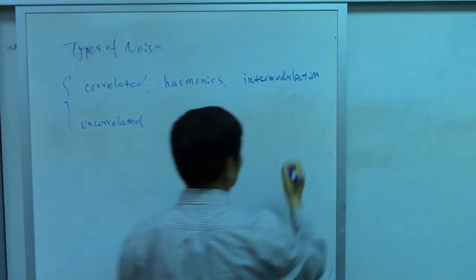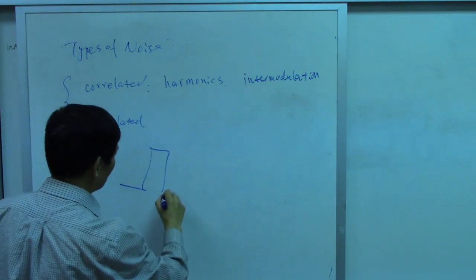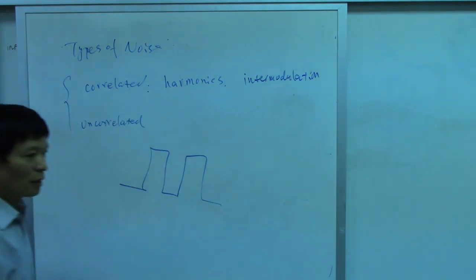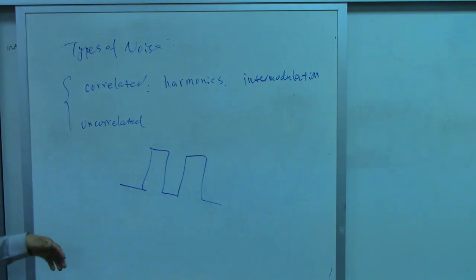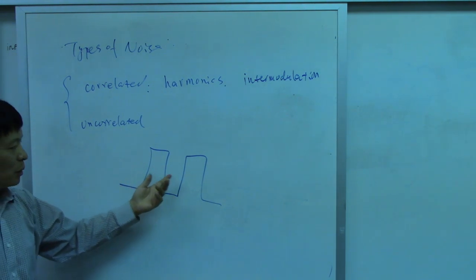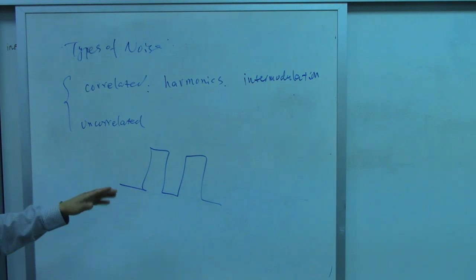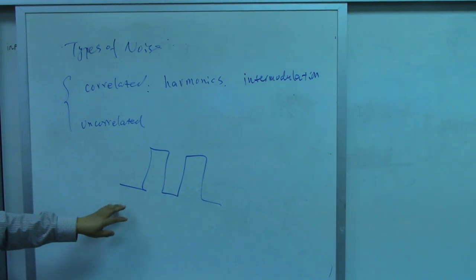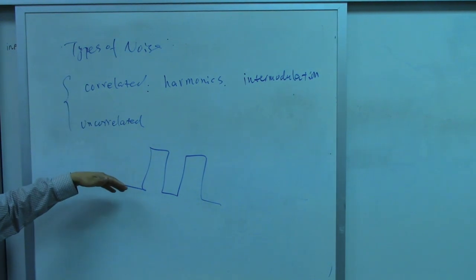Intermodulation distortions mean that if you transmit 0, 1, 0, 1 here, and your power is too large, then between all these power levels there will be some distortions. That means for digital transmission, you cannot let the power be too large. We do not say the larger, the better in terms of power.